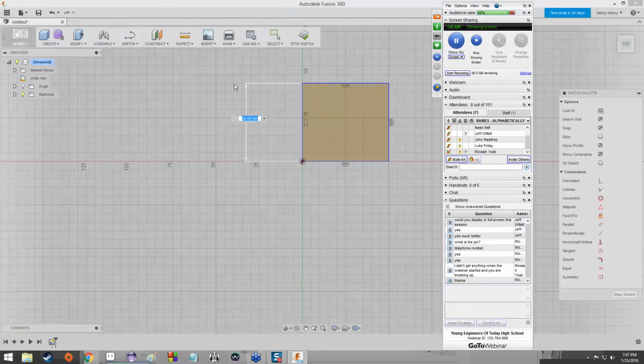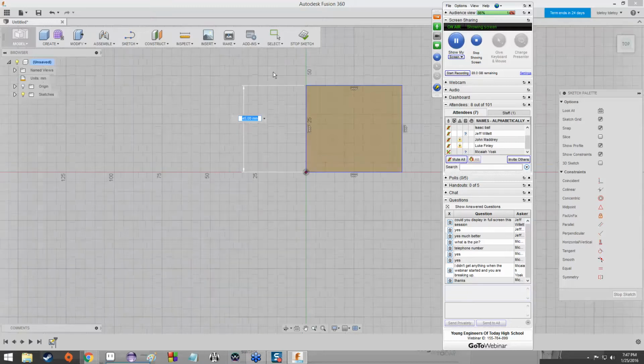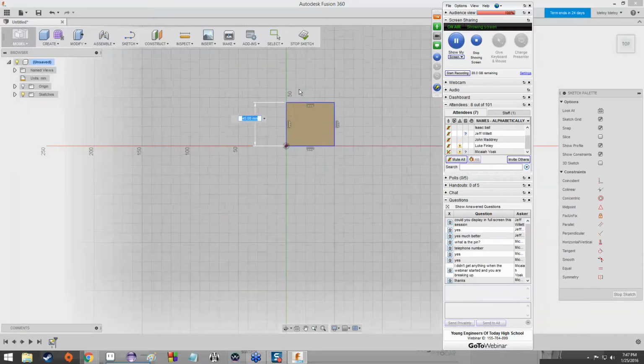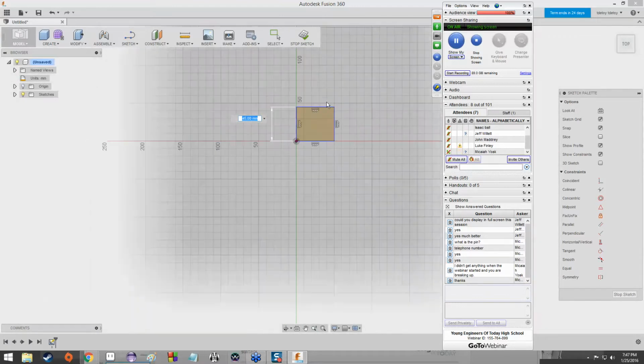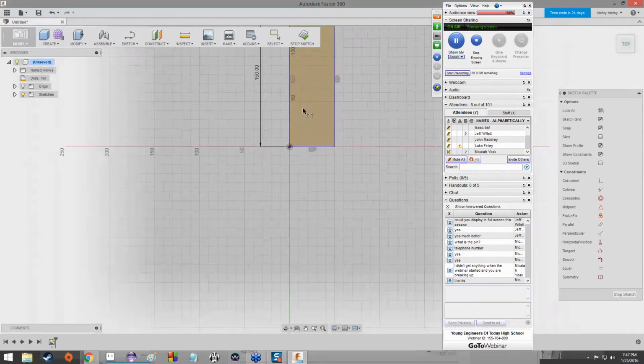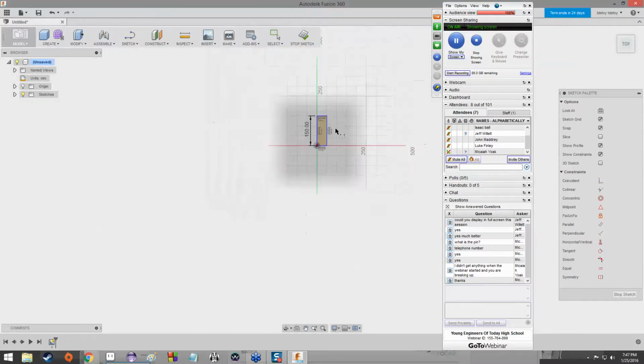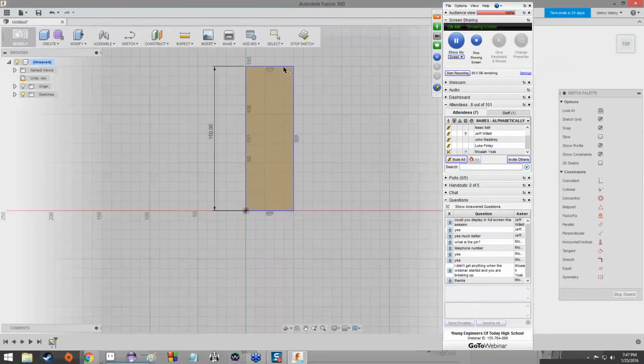Let's say I just drew this rectangle. It's almost kind of a square, with arbitrary dimensions, but I wanted it to be specific dimensions. I was like, okay, I want it to be 150 millimeters by 125 millimeters. Like that is a requirement. Well, you'll notice I only drew at 45 millimeters, but that's okay. I can say, okay, 150. And it will automatically redimension those sides in order to fit my specifications.